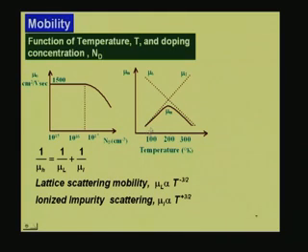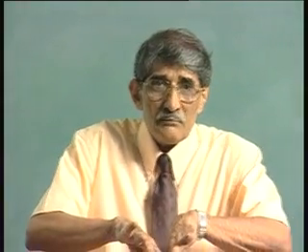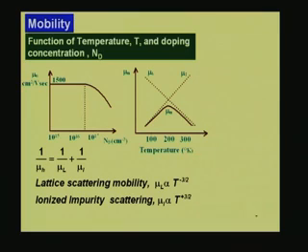Later on we will see, when you go to high electron mobility transistors with gallium arsenide, those devices depend upon this property. In the sense, the ionized impurities and electrons are not in contact with each other. There are two regions which are created which separate them out. Still, there are enough electrons, but the dopants which supply those electrons are kept in some other region. They are isolated from each other. So, that way you can make use of this thing. In fact, that is what we want to discuss later on when we come to gallium arsenide devices.